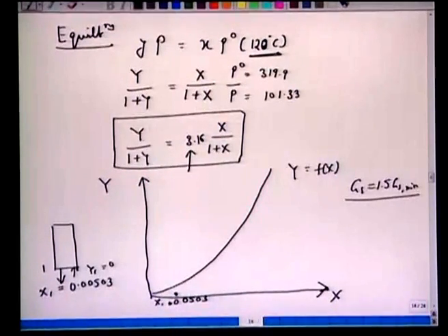Just compare this to LS equal to 1.5 times this LS minimum. Now again here, to obtain this minimum amount of solvent, of course we realize that we have to take a slope of LS by GS. LS is known to us, it's given to us. However, GS is not known to us.